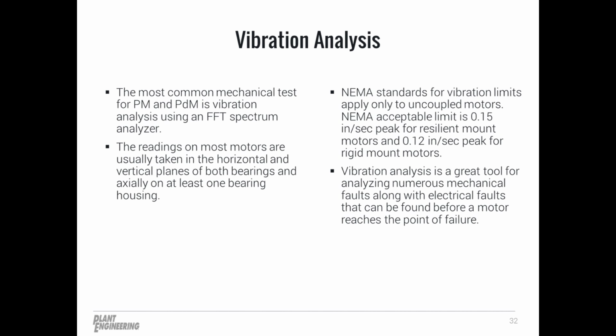And I recommend always taking vibration readings of the motor coupled to the driven equipment first. That way you can help eliminate and pick up on any signs of misalignment or coupling wear or even unbalance of your driven equipment.